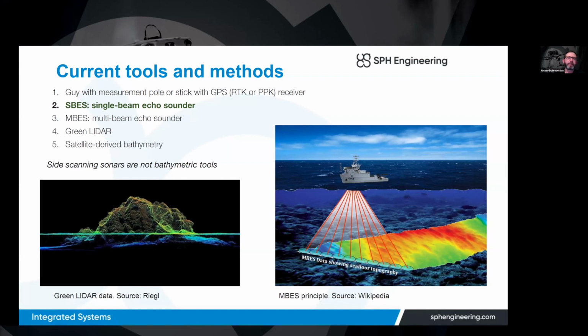And multi-beam echo sounders will require almost the same additional components as side scanners. They will require an inertial measurement unit, and they will need to precisely position every point of measurement in space. We will need to know the course or direction of the device for every measurement. It is not a very simple task to achieve that using something attached to the drone.